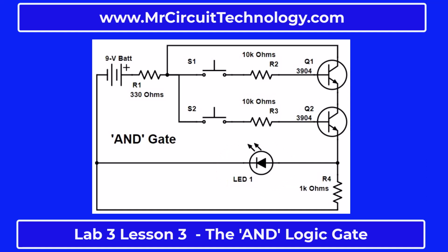Let's talk about the transistors. Remember that when a transistor is forward biased, it means that it has the correct voltages on its pins to allow electron current to flow through it. Here we have two transistors. When you press switch S1, you forward bias transistor Q1. And when you press switch S2, you forward bias transistor Q2. In this AND digital logic gate circuit, the engineer designed it so that the LED will only light up when you forward bias both transistors at the same time. To do that, you have to press S1 and S2 simultaneously.